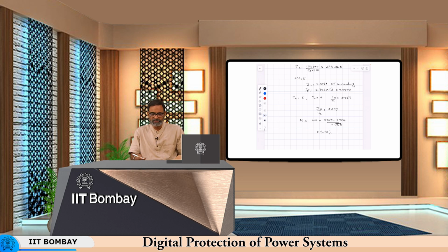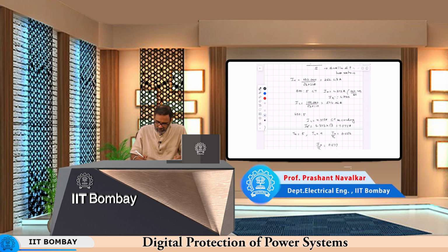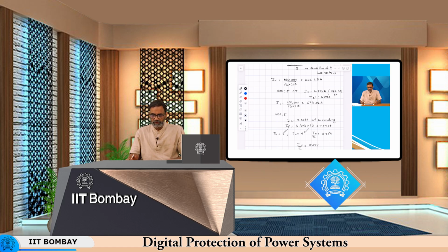All the differential relays that we said, transformer differential relays, are generally variable percentage bias differential relays, with a differential of 15 to 60% that can take care of this. So that's how the two steps for relay setting are done. First is the phasing and second is the tap selection. In the relay tap, depending on this, you will choose 5 for the high voltage side tap and 9 for the low voltage side tap. This is how the relay setting for the differential relay for this 100 MVA transformer is done.